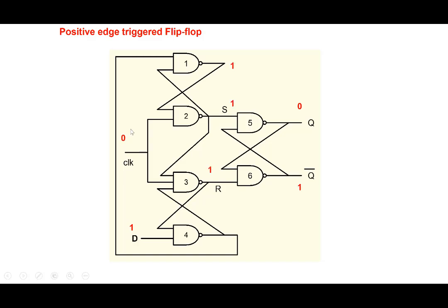All right. With this value here, when the clock is 0, the NAND gate output is 1 here, this is 1 here, and so this particular latch is basically in a hold state. It's in a hold state, and note that you could change anything here, but because the clock equals 0, it forces it equal to 1.